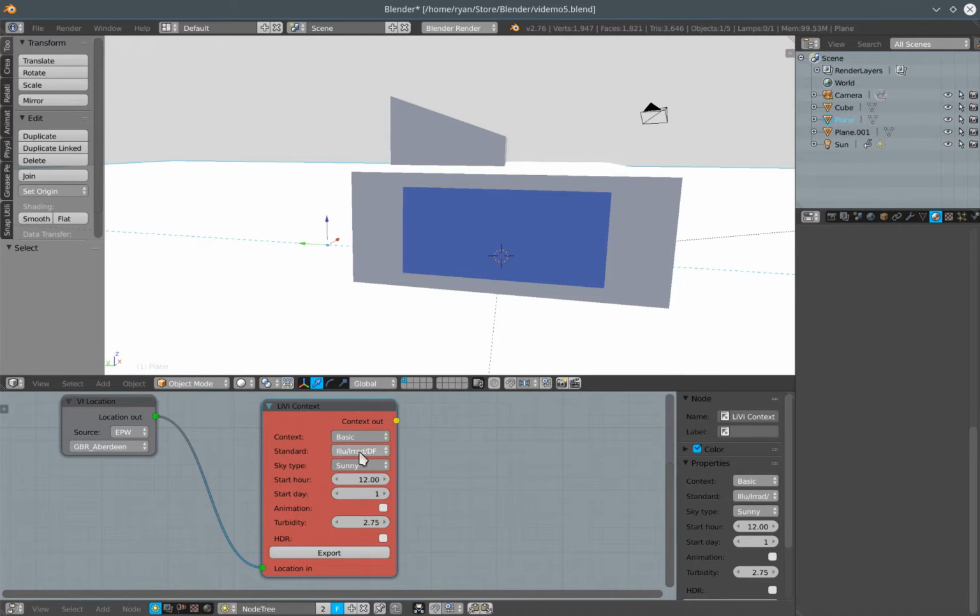Another new feature of version 0.3 is that instead of having to do a simulation for illuminance and a simulation for irradiance and a simulation for daylight factor, where it's actually a single metric or a single value that we can calculate, and then it's just a conversion of that value into these other values, they're now clumped into one menu item.